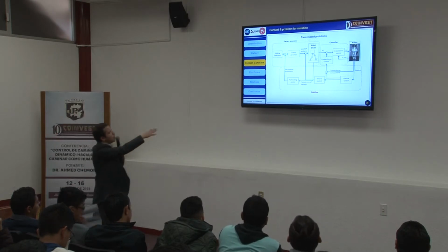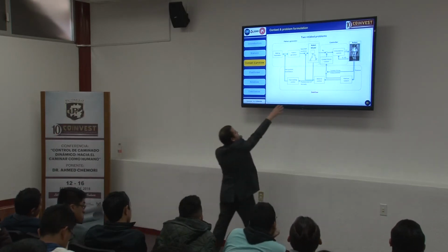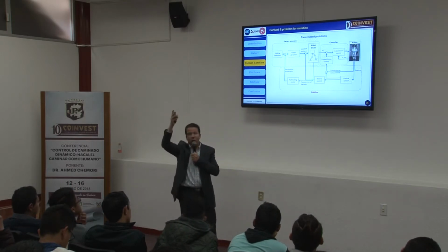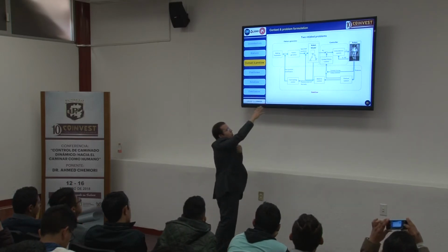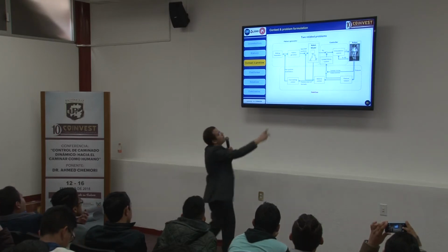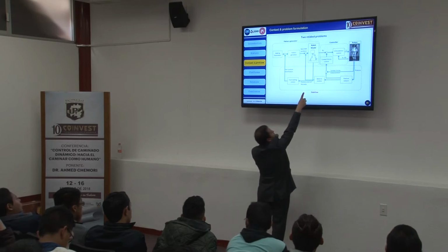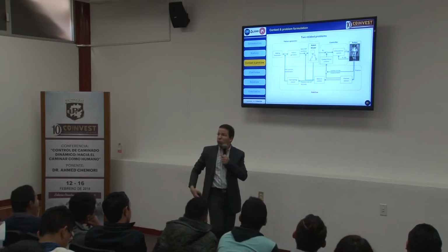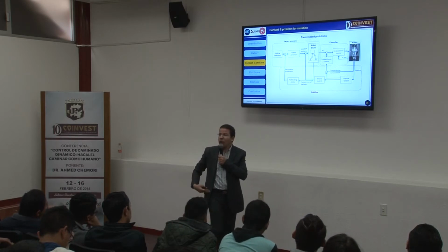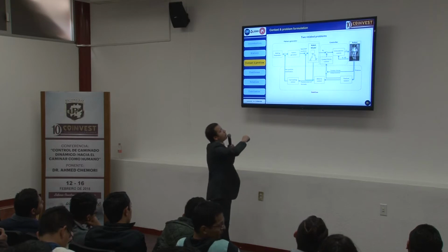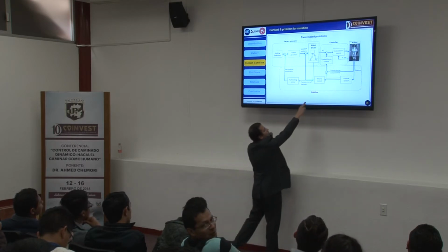Now, to answer what we need to reproduce a human walking on a humanoid robot, I can show you just an example. Don't worry about the contents inside. I just have to emphasize three things. This is a control algorithm, or control scheme, if you want, and it includes three main things. Here it's the controller itself. Here it's the pattern generator. It's the trajectories. I want to do periodic motion. How will we generate these trajectories, this motion? This is what we call the pattern generator. And the last one is what we call the stabilizer.